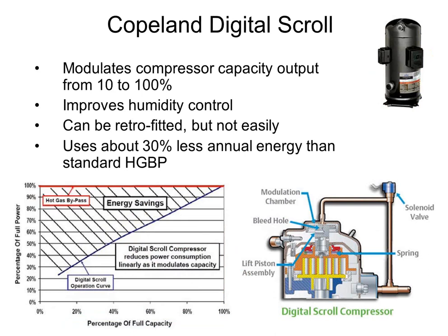And the way a digital scroll compressor basically works, I wish I could put the video on here. The scroll compressor has 2 swirls kind of intertwined. If you ever looked at the inside of a scroll, let's see if I can draw it on here, because I'm a really great artist, right? I might have this swirl like that, and then I have another one that's swirled the other way, and those 2 things set into each other. And then as they swirl, they compress the refrigerant into the eye. So that's basically how those guys are working.